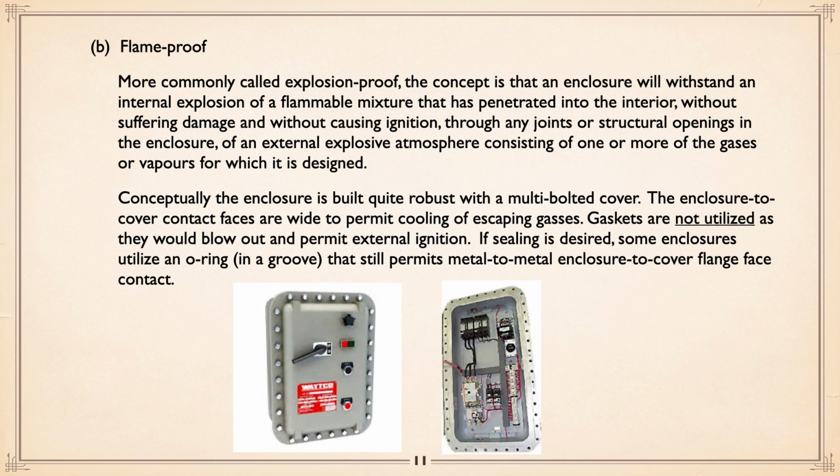I mention here, if sealing is desired, you can get some enclosures that use an O-ring and a groove. You still have a lot of metal to metal to cool the gas, and you have an O-ring that will seal out liquids. And to be honest, if there's an internal explosion, goodbye O-ring.